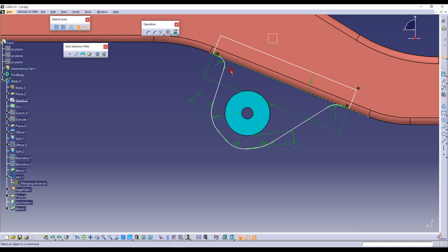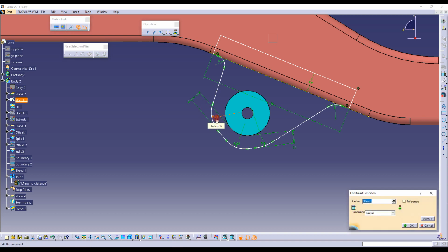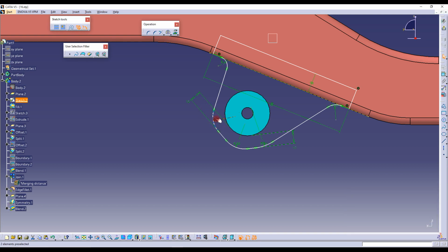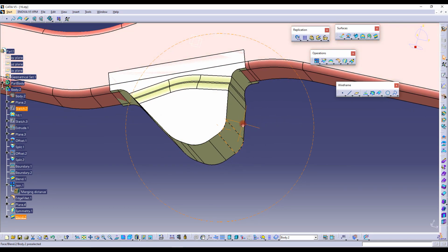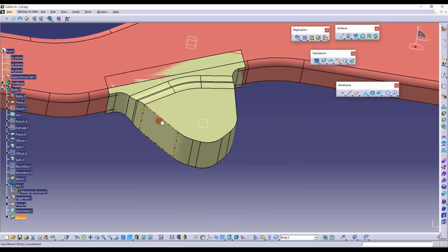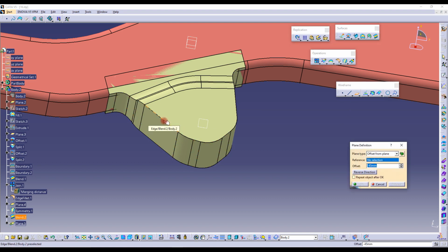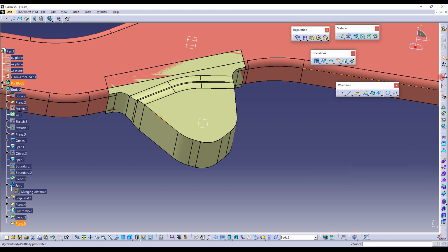and let's reduce this to 30. Let's keep it at 25. Just move this point, slide it up and come out of the sketch. Next, we will create a sketch on this plane. So whether we can directly sketch on it. Okay, we are not able to sketch on it directly. We have to create a plane with respect to two lines. Select this line and select this line and create a plane there and start sketching on that plane.